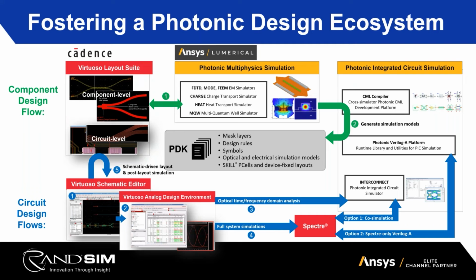Users can also perform full system simulation on both their electronic circuits and photonic circuits by leveraging Cadence Spectre and Lumerical INTERCONNECT. This is also available for the Verilog-A platform, and the schematic design can drive circuit layout, and layout can be back annotated to the schematic for post-layout simulations.